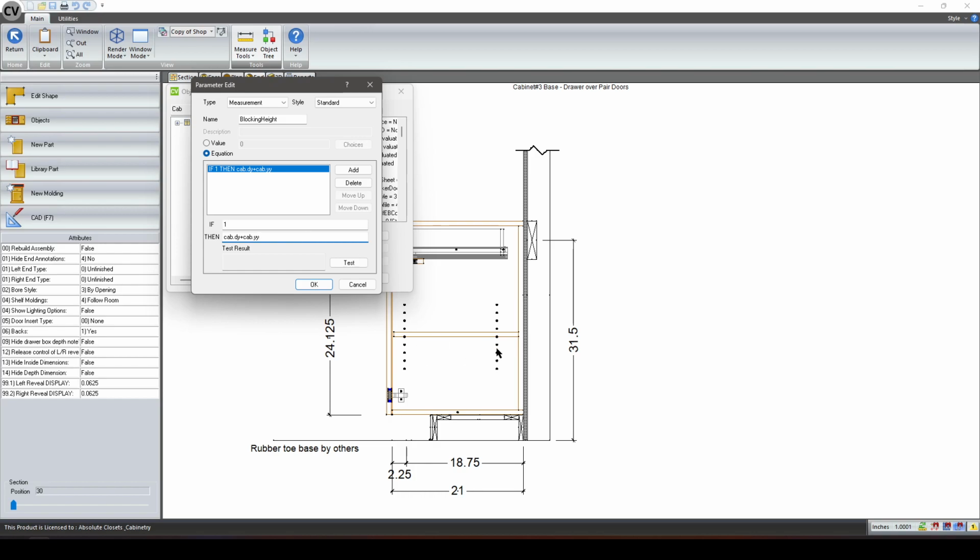Because if you're unfamiliar with this, while you're in the assembly editor, your cabinet's X, Y, and Z values are not really what they are in the room. I'm not going to go into that a whole lot in this video, but basically I need to reference cap.yy here, and I'll show you. The cabinet height plus the 4-inch toe kick that I know I have is going to be 34.5.